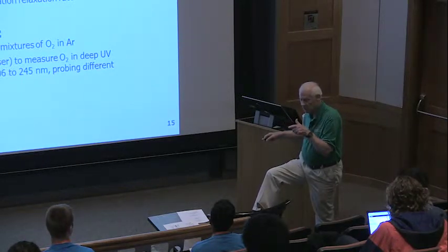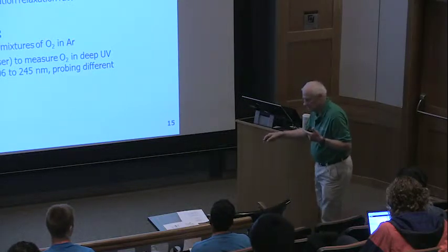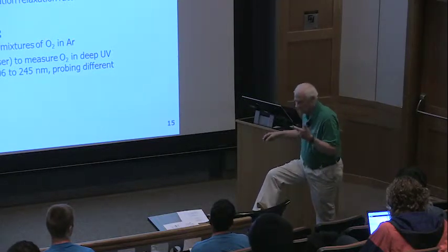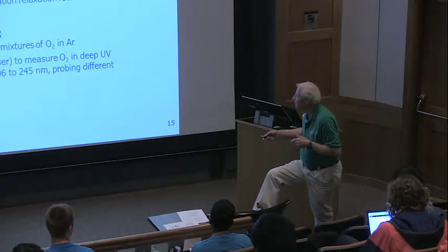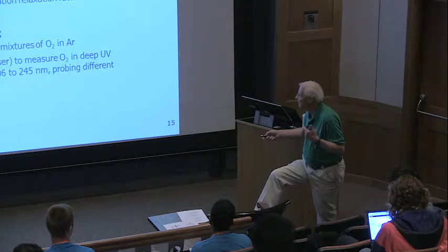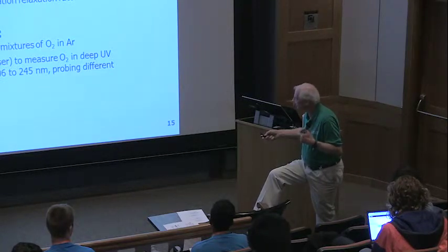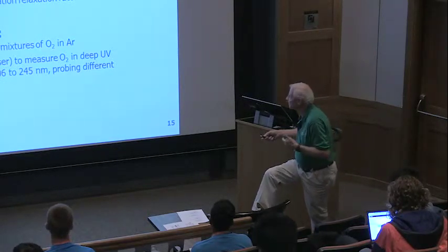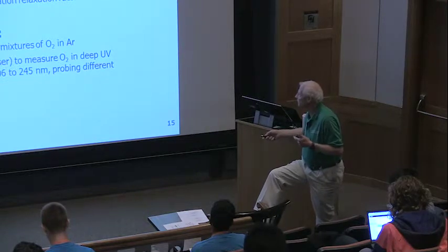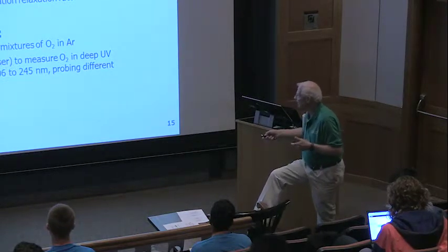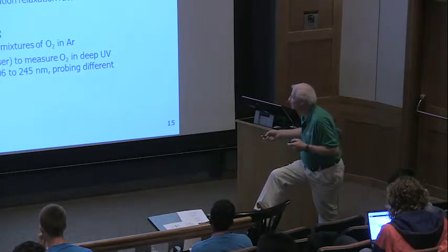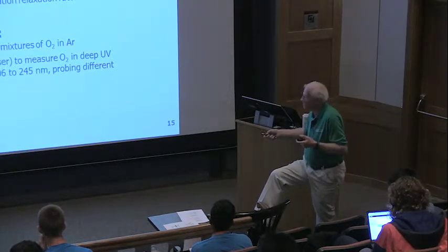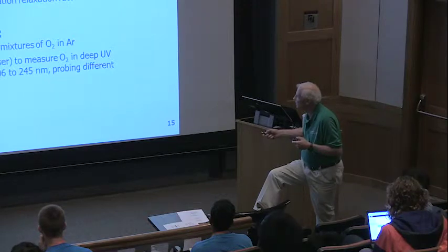The shock wave is taking that static air and converting it to higher temperature air. And if you want to compute the flow field about this body, you have to take into account the energy transfer between translation and vibration and even the chemistry. But right now we're just doing the vibration, like I say. So you need to have a model for the rate of change of vibrational temperature with the flow field. So we actually want to measure oxygen because oxygen is an important constituent in air.